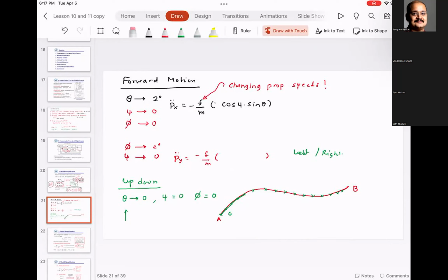But then clearly the pressure sensor values are going to be different depending upon where you are on the earth. So for that, we do some type of a calibration. We set up the Mambo at the ground level, we get the value of pressure, and then we raise it, we measure the pressure, and then we find out the difference in the pressure and relate that pressure difference to change in the altitude.